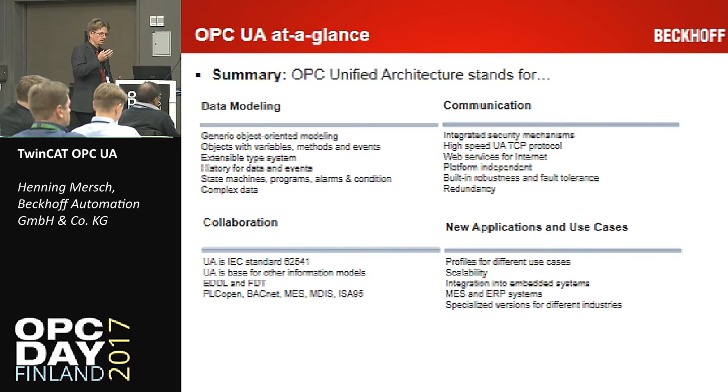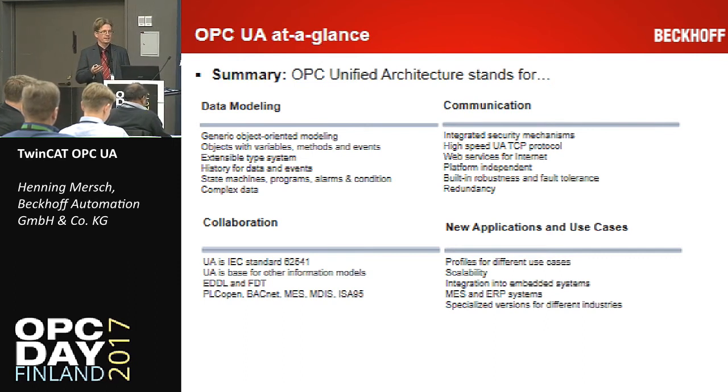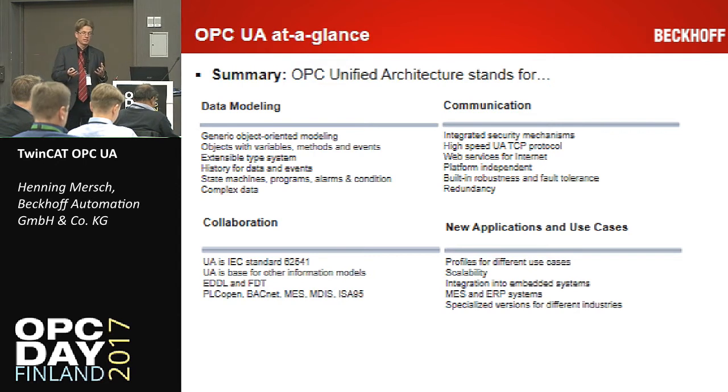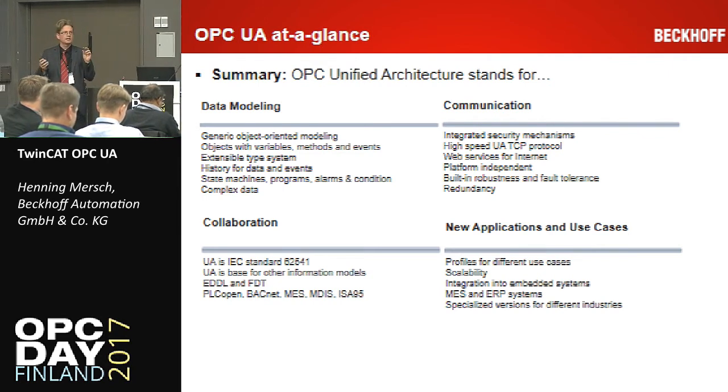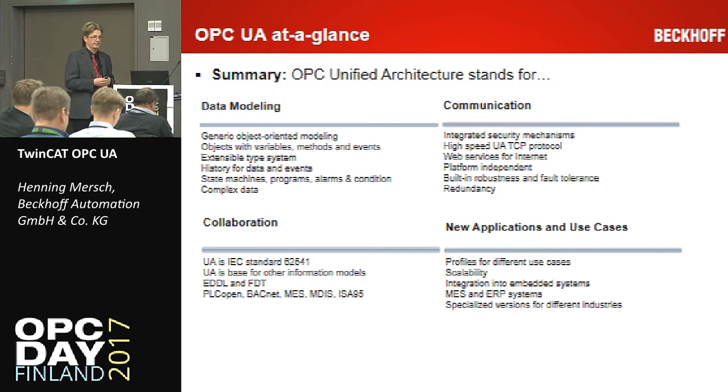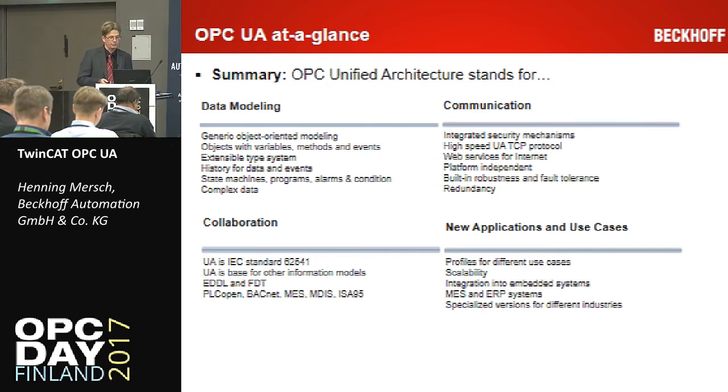then you need to start on top of the OPC UA base data types. There's nothing which is helping you. So we need more of these companion specification models which are just providing the base data types, enhanced data types, like an IP address. Otherwise, we would end up having an IP address defined in the whole range of companion specifications, slightly different, and all the types are not matching each other, and we have converters again and again and again in the future. So this might be a demand we need to address in the future.